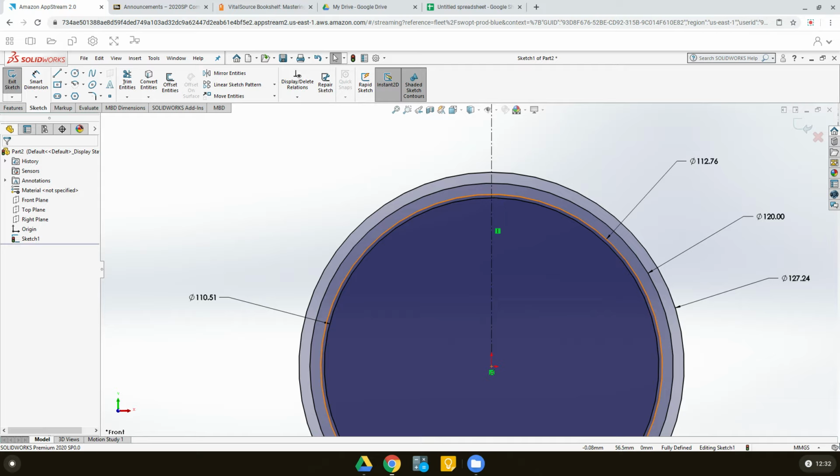because as I said before, the profile of the gear tooth below base circle doesn't have to be very specific, right? That is just for the manufacturing clearances. So we just need to worry about the profile of the tooth above the base circle. And then once we create the profile tooth, if it comes out of the addendum circle, we can chop it. Whatever the profile of the tooth above the addendum circle is not important, we can chop it out, because we just need to go up to addendum circle, right?